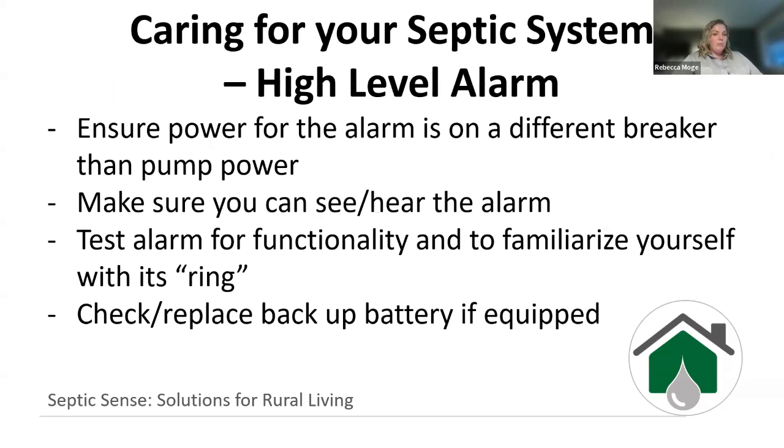A high level alarm. Again, in the last 20 plus years, I believe it's been a requirement to have a high level alarm. Its job is to let you know when you're having troubles, so to warn you before you have sewage in the basement. And again, it can be installed at any time. So if you don't have one, you should get one and it can be installed.